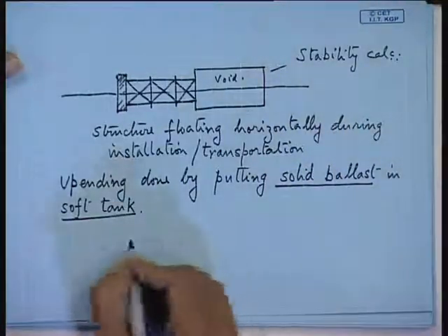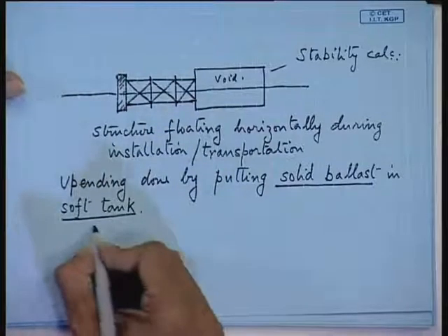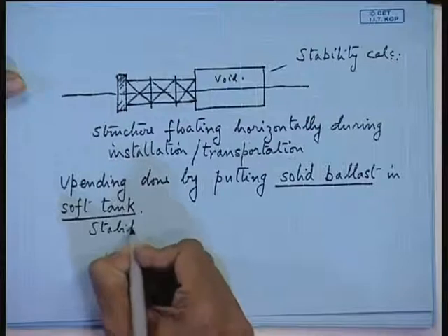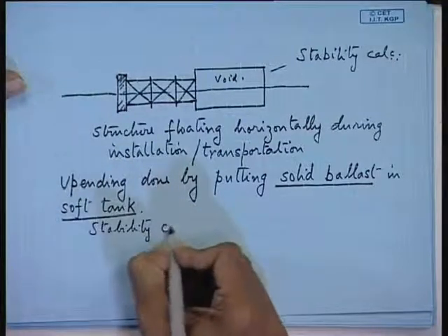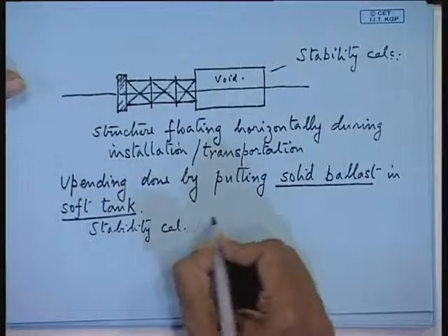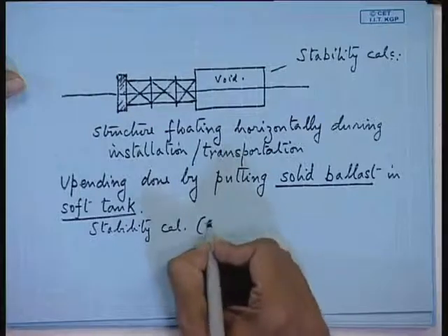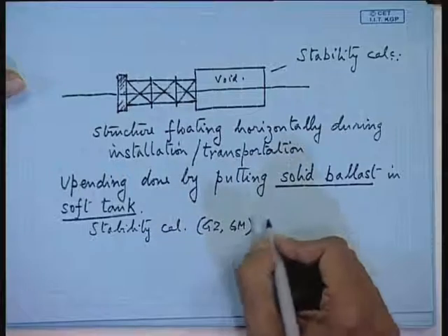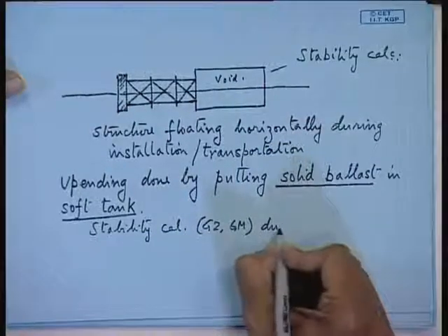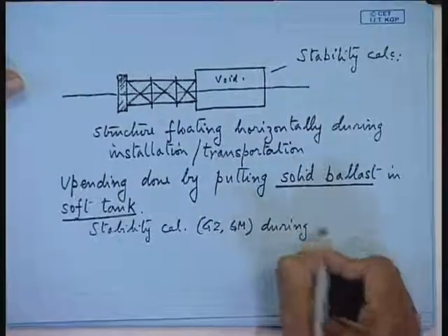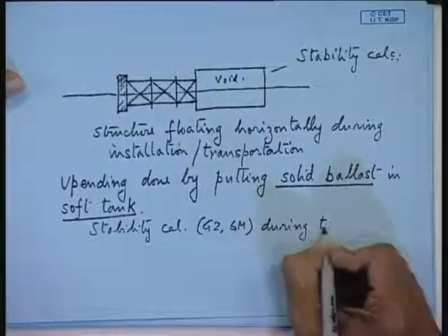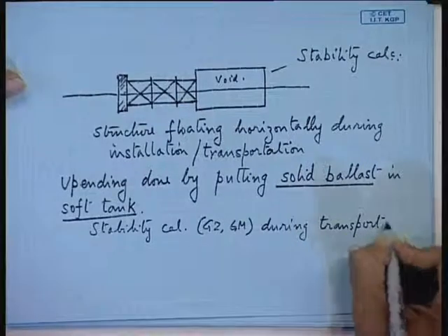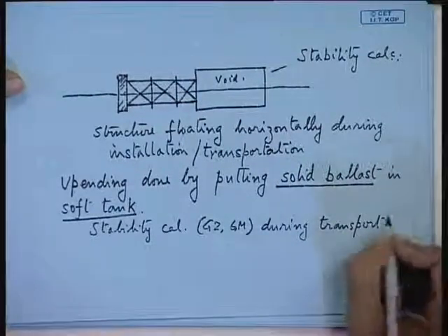So, naval architects, if you go to offshore companies, you will be asked to do stability calculations. Stability calculation, especially your calculation of GZ, GM during transportation and installation. So, that is one of the main reasons why naval architects are on the job.